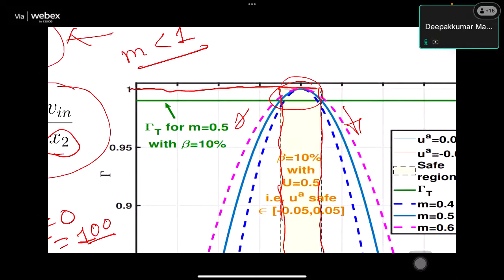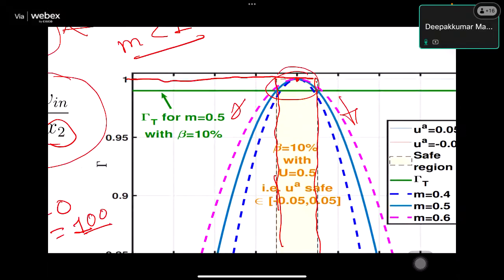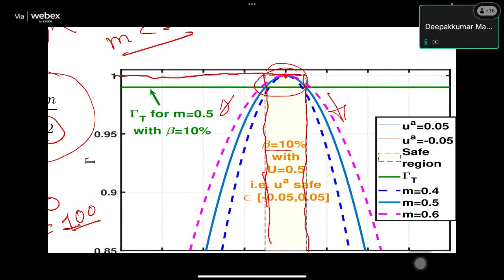But we are not saying that the moment you cross operating point 1, we can classify this as an attack, because we have to give some safe region of operation. So this is the region in which you are operating. That's why we are saying that within 10% variation is fine. Within 10% we will say that the system is operating in a healthy scenario.